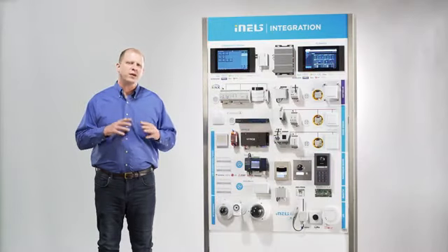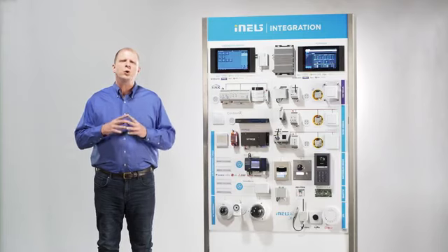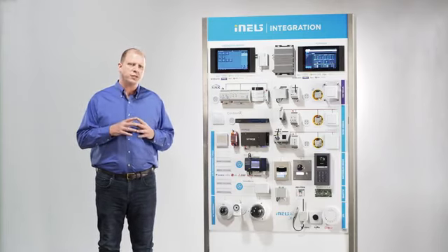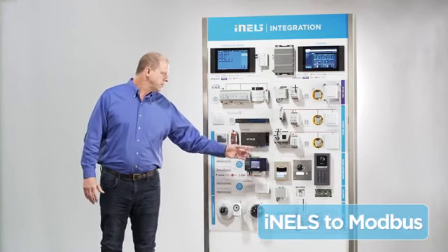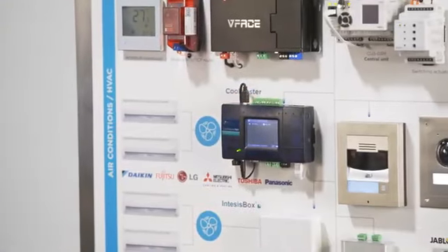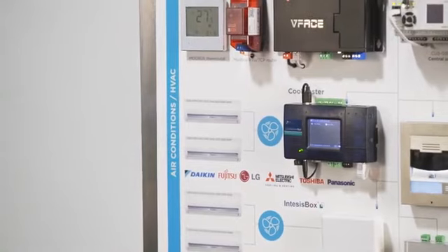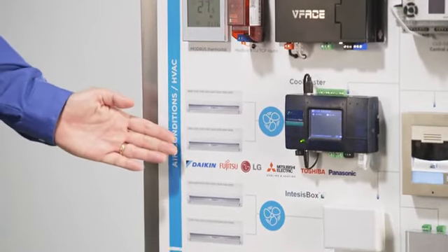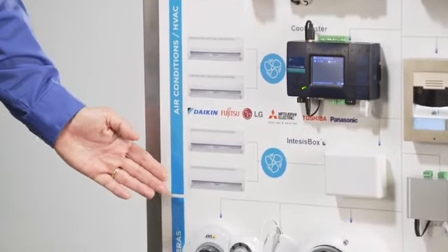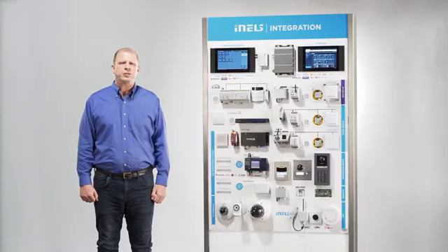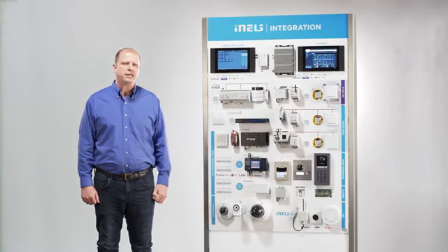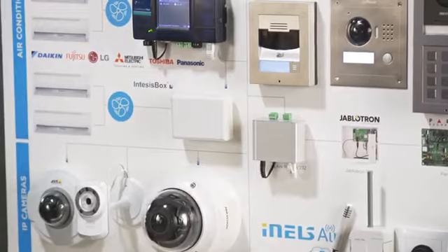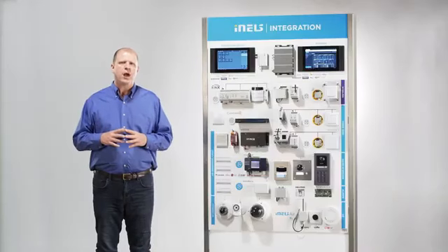Another interesting feature of Connection Server is to control Modbus devices through a data converter using the protocol Modbus RTU via port RS485. Connection Server gets translated communication and the user gains access to air conditioning control by LG, Daikin, or Mitsubishi. The other devices using Modbus RTU can be accessed via ELAN API. The data converter can handle even more.